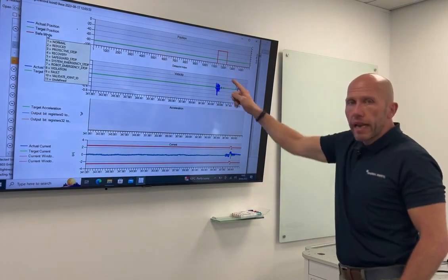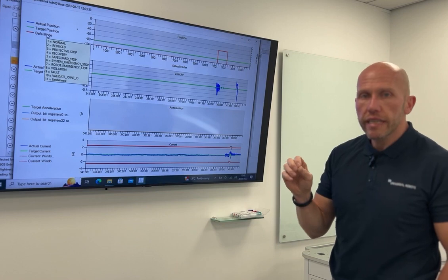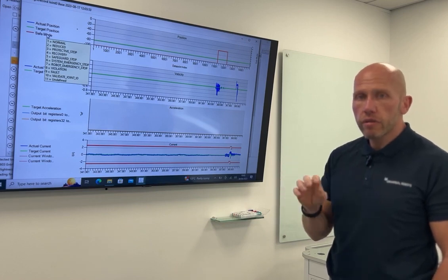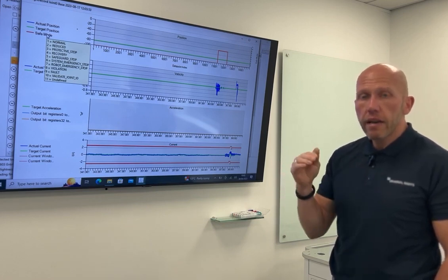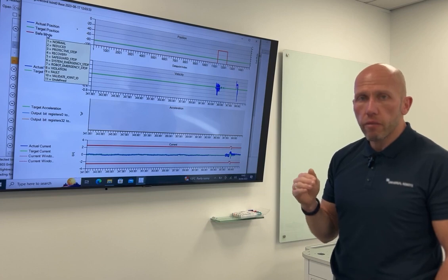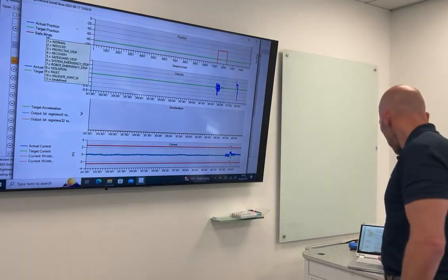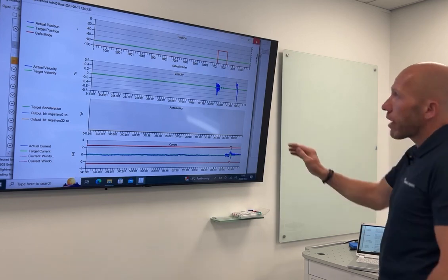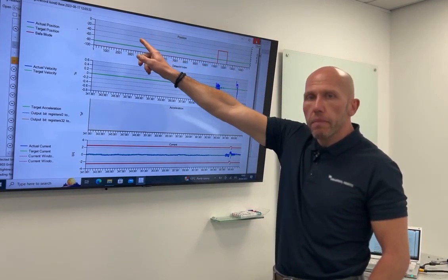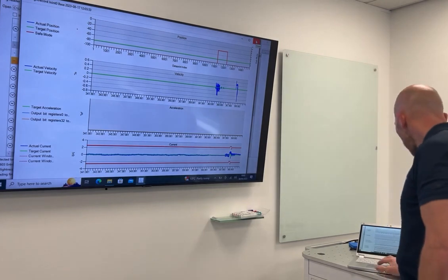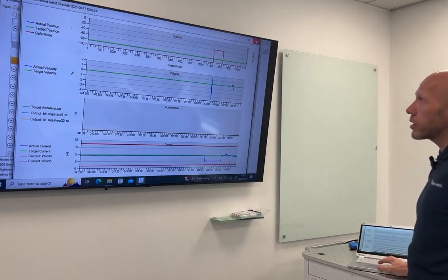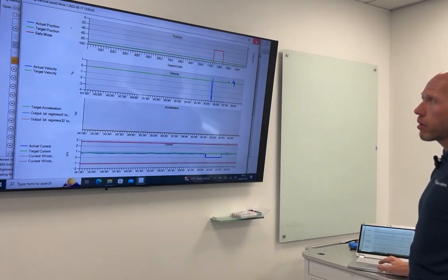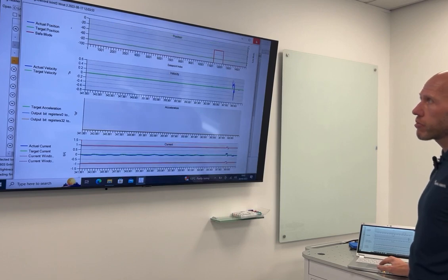We can see the script line number. So if we wanted to interrogate the log file further, we could actually look at the script line and find out what part of polyscope the error was occurring. So I'm actually going to close this down. What you'll see, it gives you 6 graphs. My first graph is the base joint. So now I can close that down. It's shoulder, elbow, wrist 1, wrist 2, and wrist 3.